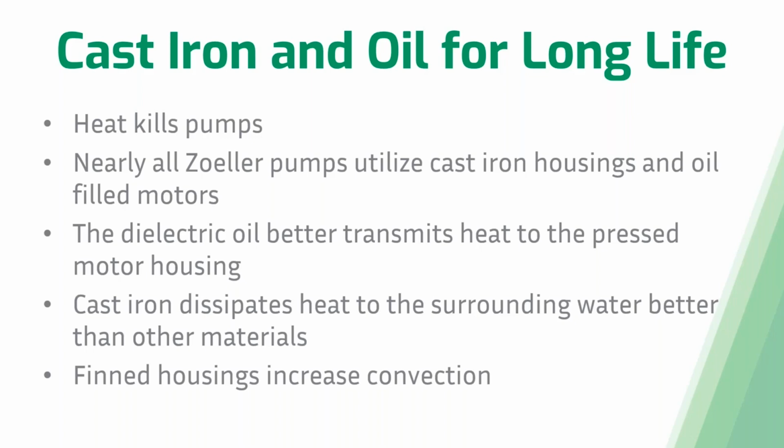Another thing to note is that we have finned housings on our pumps. And this helps increase convection, which is just increasing the amount of heat that is transferred between that pump and the surrounding water. The more contact that you have with the surrounding water, the better that heat is going to transmit out.